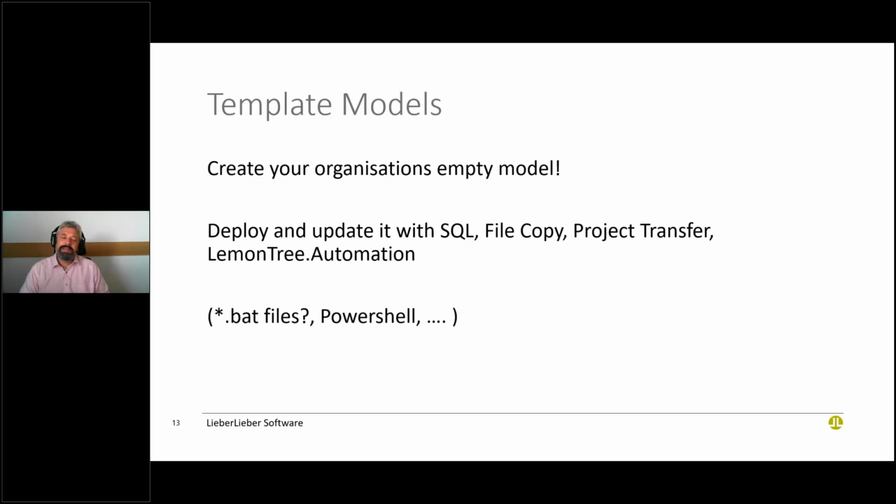Also, if you use MDG technologies, my strong advice is to import them in the model. Why? Because it happens that you need to go back to an older model and check what the guys did 3 years ago. If you only have the MDG technology on your computer, the latest version, you might run into trouble reading the old model in a proper fashion. So if it matters, really import the MDG technologies always in the model or even in your template models. It's really something that pays off. You know, document generation templates, all these things belong in the template model.